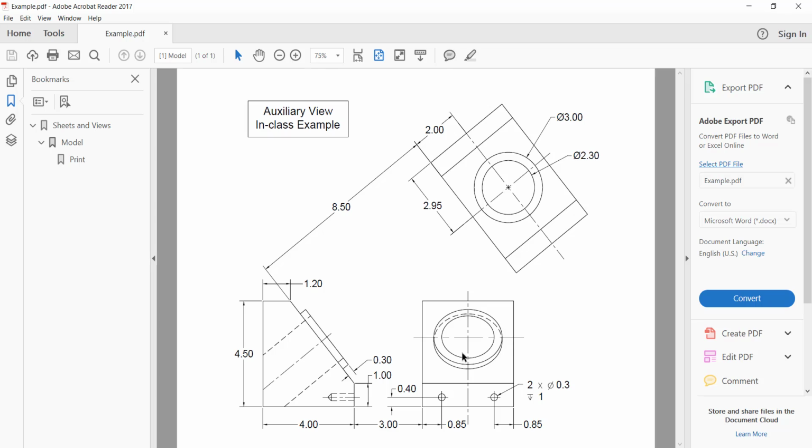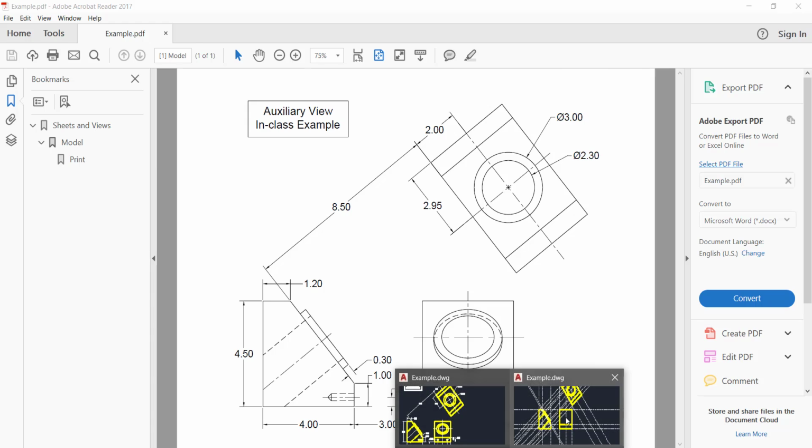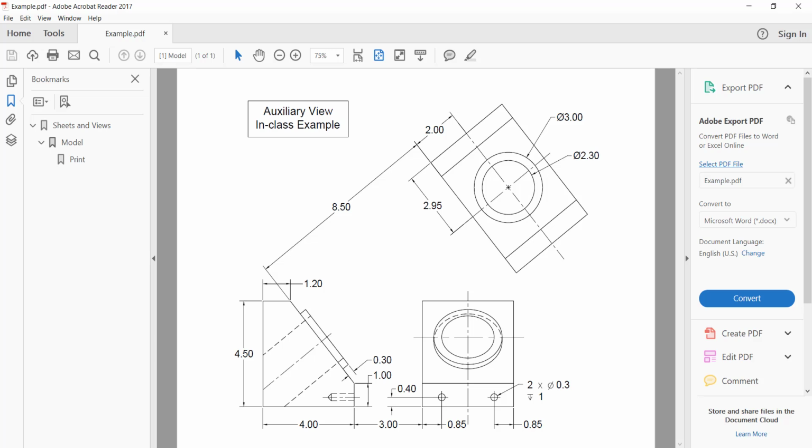So we're going to draw the bigger one and copy the bigger one below here. So let's go back here. Oh, we haven't got the dimension yet. So we can project here, and this is the center. So the center is going to be here, this center. And we know the top point, so we know the minor diameter. And the major diameter should be the same as the auxiliary view because it's not accumulated in this direction. So it's a 3. So in other words, 1.5 as the major radius.